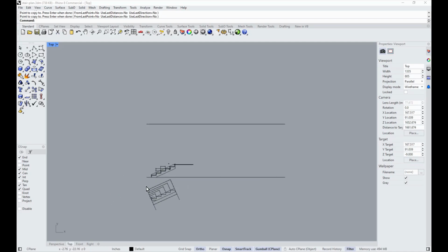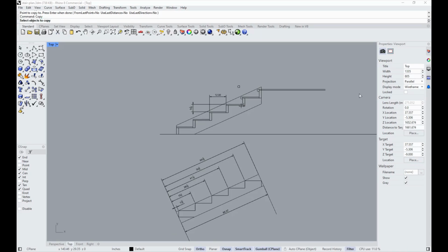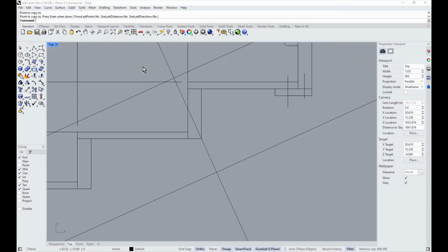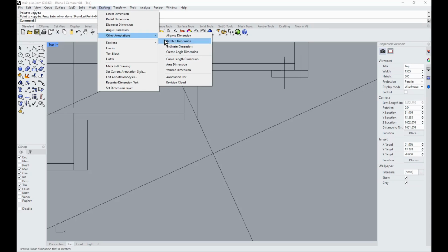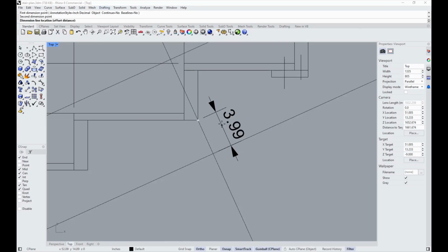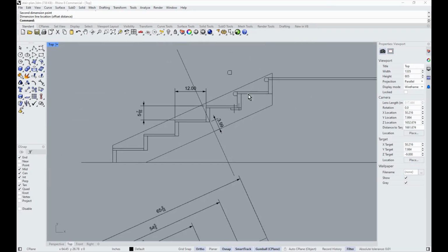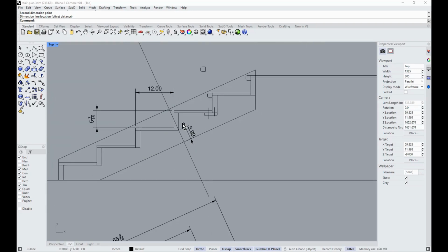And one last word of note on this is just be careful of this dimension. Let's see if I can copy something over so you can see what I'm talking about. These are structural. People are walking on these things. So this pinch point here, you're almost on the floor system, and you're making something that is, let's see, the other dimension, the angle dimension, there we go. So that's like 4 inches deep right there. It's almost like they're walking on a structure that's made out of 2x4s. Granted, a 2x4 is actually 3.5, but hopefully you get my point, that is the pinch point.